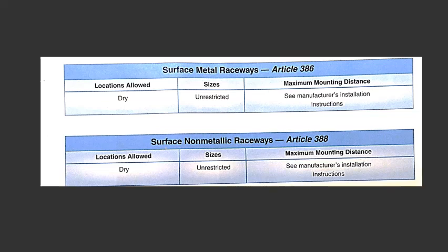Surface mount raceway is mounted on wall or ceiling surfaces only in dry locations and where it will not be subjected to physical damage. Elbows, connectors, and couplings and boxes are designed to be electrically and mechanically continuous and compatible. It is useful in existing facilities when appearance is important and new wiring cannot be pulled through walls.